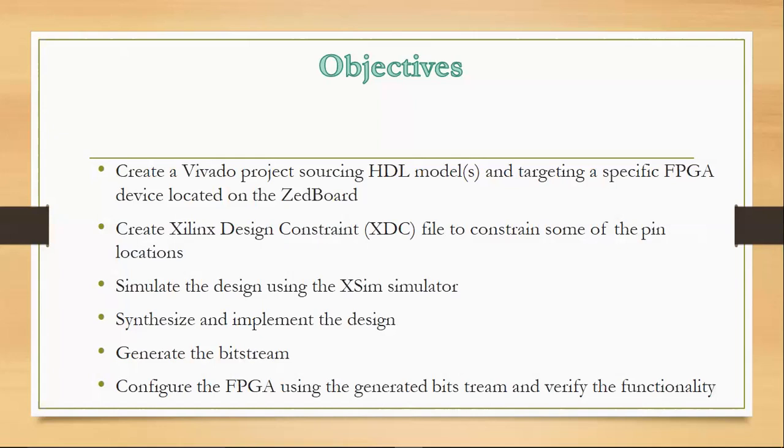Simulate the design using the simulator provided by Xilinx. Then synthesize and implement the design to the FPGA and generate the bit stream. Configure the FPGA using the generated bit stream and verify the functionalities. These are the objectives of today's practice.